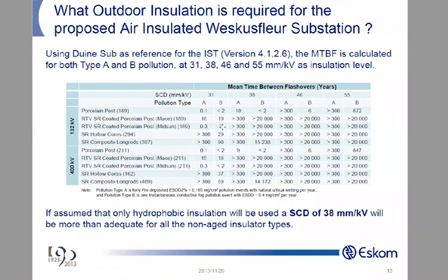So, my goodness. So you specify out there, I would like an RTV coating. It must be hydrophobic. And both of these guys tend to come back. And now how do you know which one to choose, and how do you know which one is performing better than the other? Get your pollution performance curves, use it, and make a decision. See the power of the tool, power of the process.